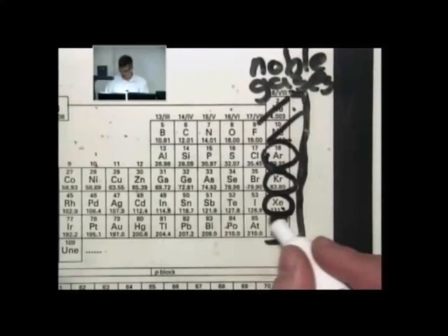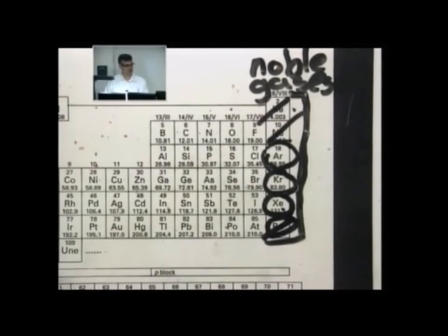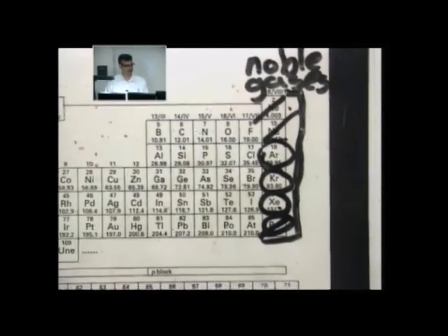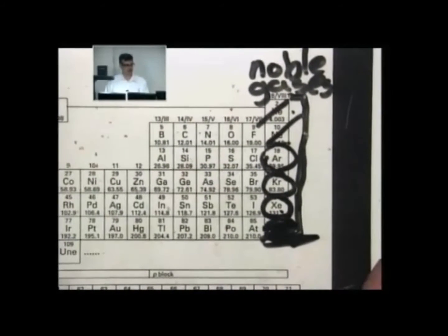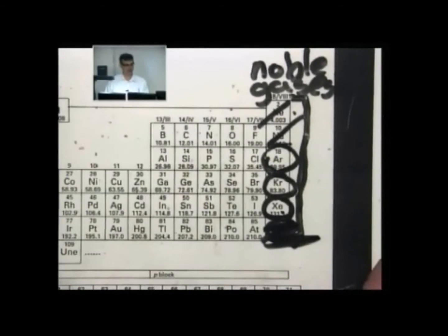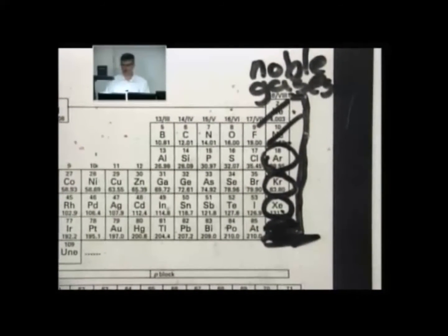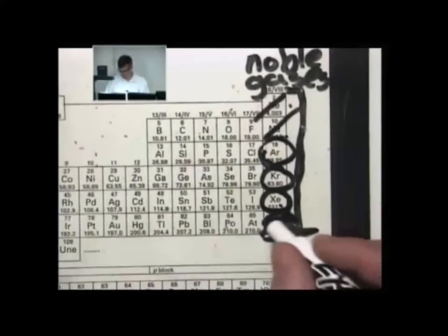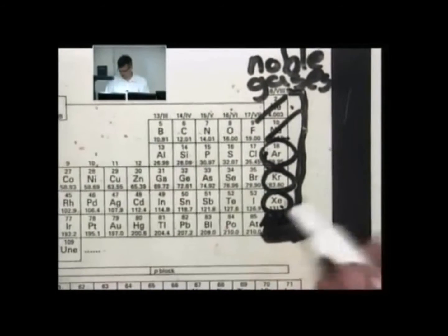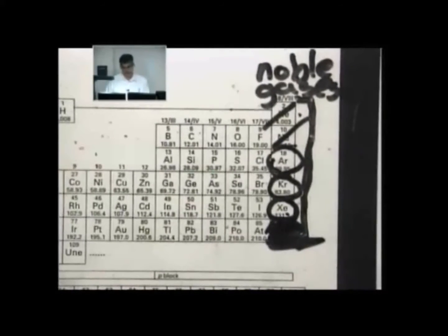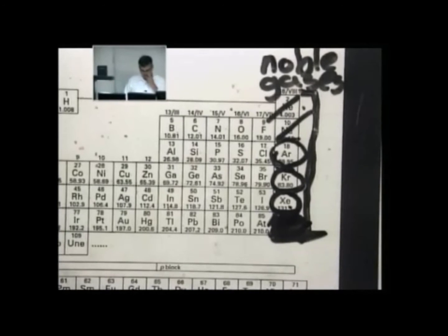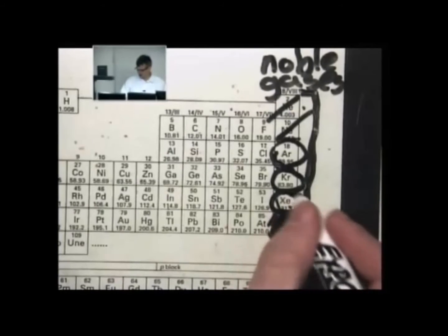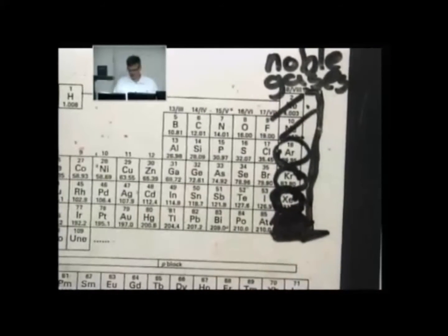Radon, of course, is the densest of them all, but there's, of course, some philosophical and biological reasons why that's difficult to procure and use as rocket fuel. So we don't usually use that one as a propellant. It's highly radioactive. It decomposes into lead and some other particle naturally. Although there seems to be an abundant source in my basement for some reason. No, just kidding. So these are candidates. Xenon is particularly well suited. So xenon and krypton, I think, do the lion's share of propellants for ion drives.